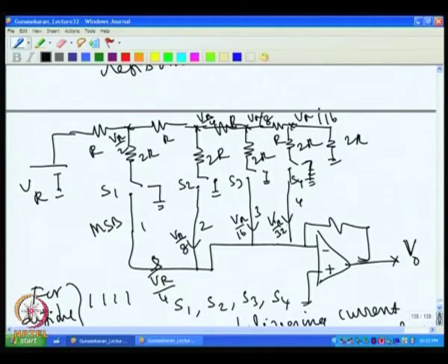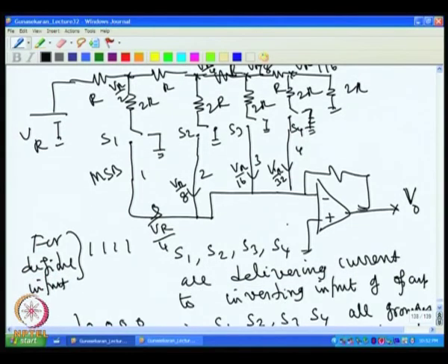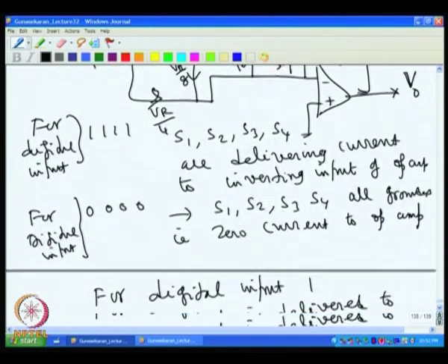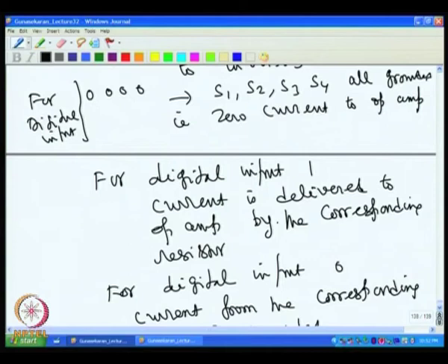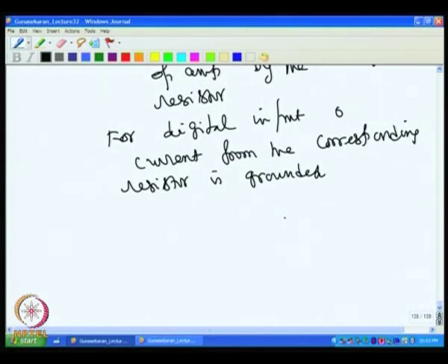That way the current is binary weighted, and you get an output voltage corresponding to the digital weight. This is the most popular DAC because it needs only 2 different resistors, which are repeated depending on the number of bits required. Maintaining accuracy with only 2 resistors is much easier, which is why this is popular.